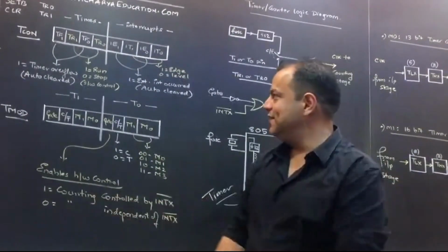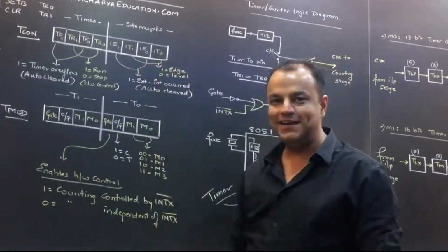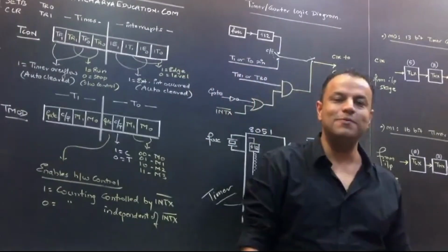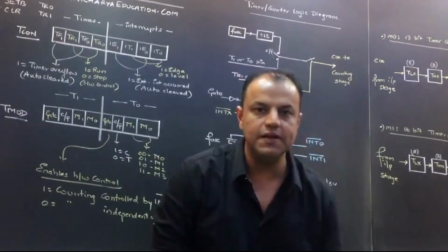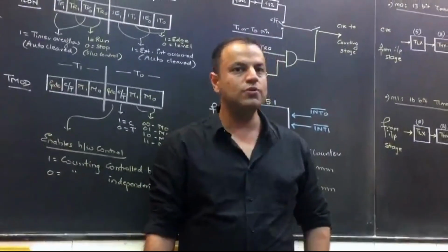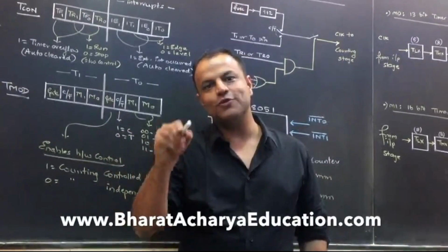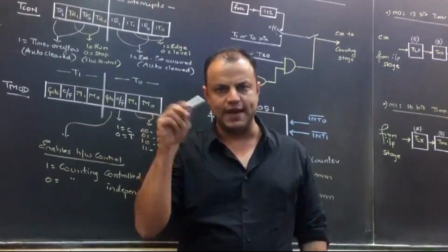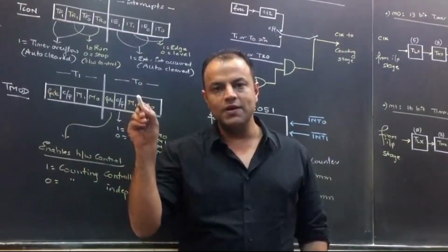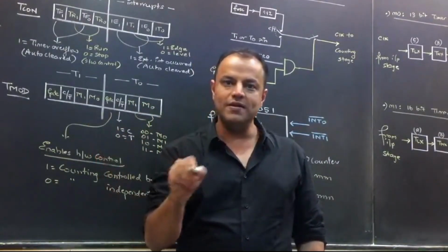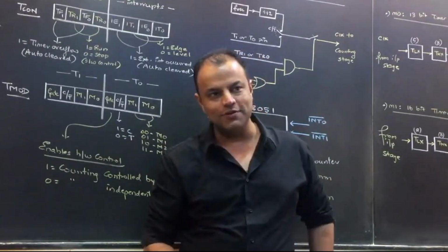Finally, you have IT1 and IT0. They are interrupt trigger flags. They're called interrupt type, but basically they give the trigger. I'm sure you know there's something called edge triggered and level triggered. If an interrupt is recognized on an edge, could be rising, could be falling, these are active low, so it will be falling, but anyway, when an interrupt is recognized on an edge, that is called edge triggered. When it is recognized on a level, that's called level triggered.